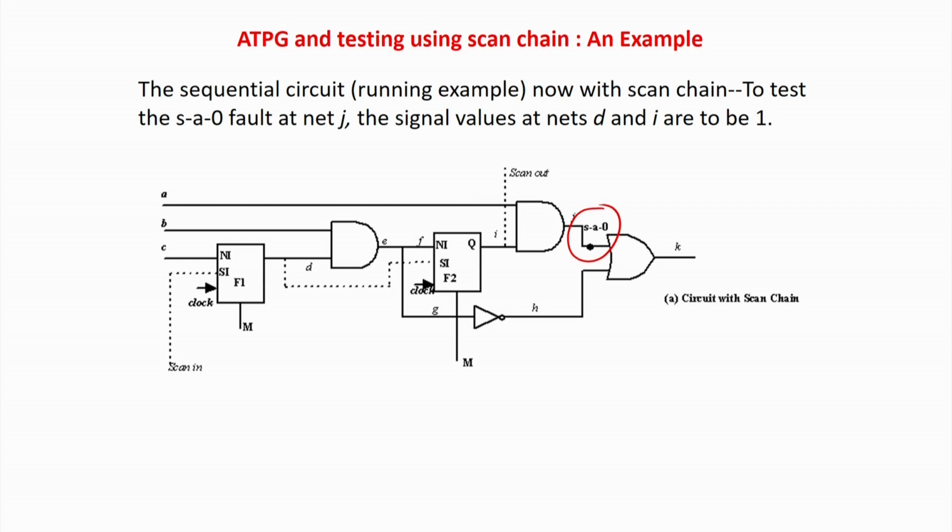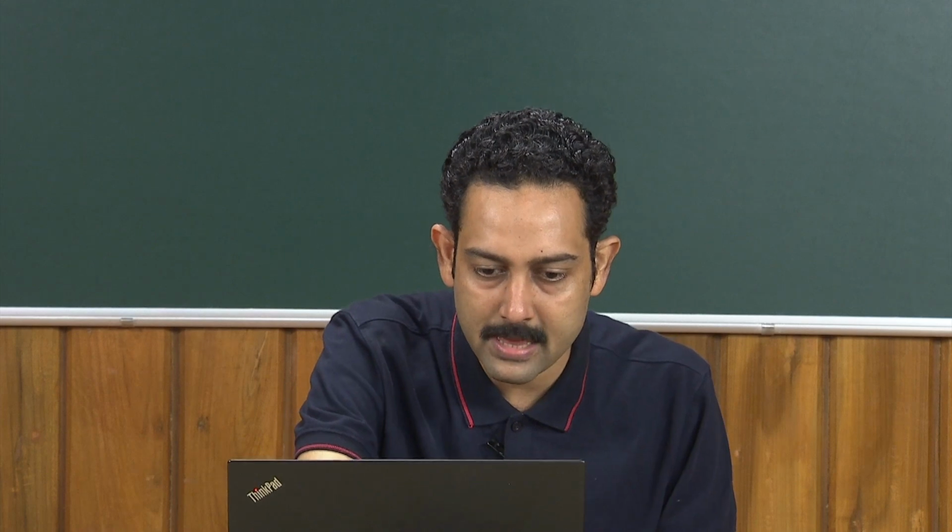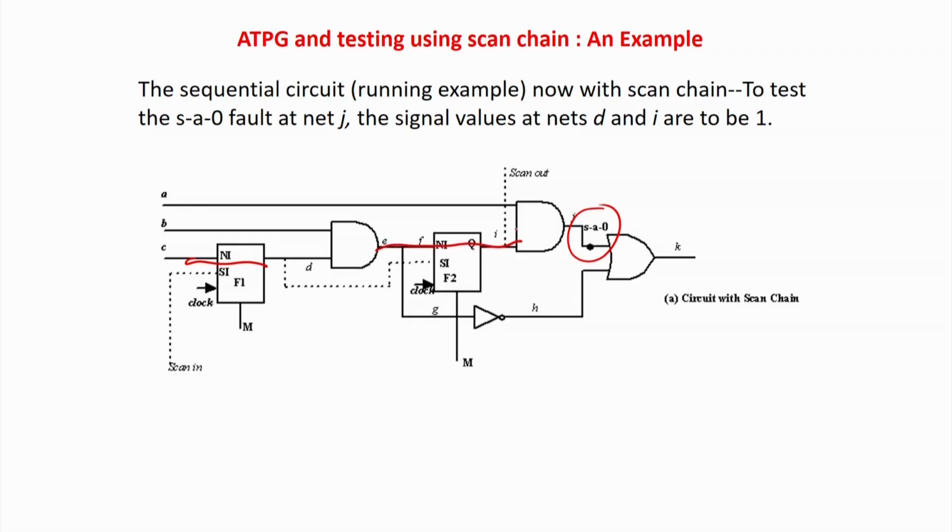So simple, first you have to do an ATPG. So what are the steps? Now I am going to take the things more mathematically, that what are the steps to do it. First basically you have to forget that there are flip flops and you have to go for an ATPG. So I just say that there is no flip flops over here. Just assume that they are directly connected. For time being, you just assume that. So I am making a pure combinational circuit by removing all the flip flops, connecting the input to the output, and your job is done. Then go for ATPG combinational.